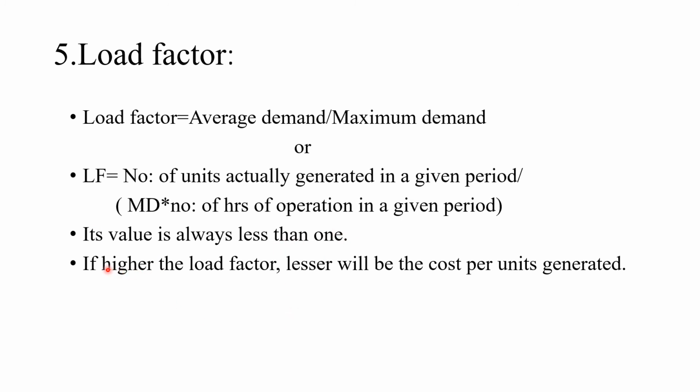And one more point is that if the load factor is higher, then lesser will be the cost per unit generated. That means if the load factor is higher, maximum demand is very less. That is the good condition for the lesser cost for the production of units.